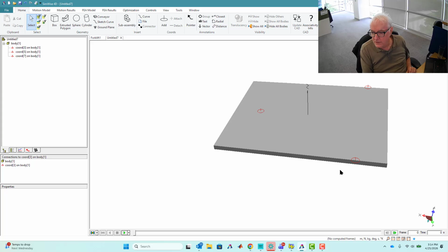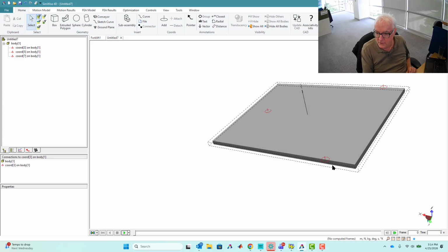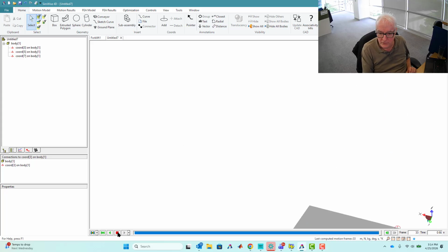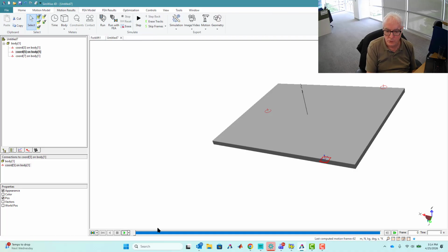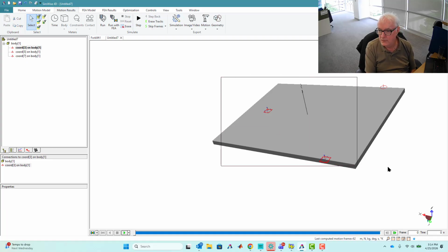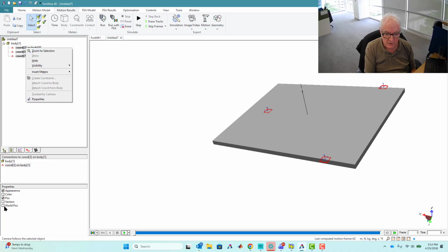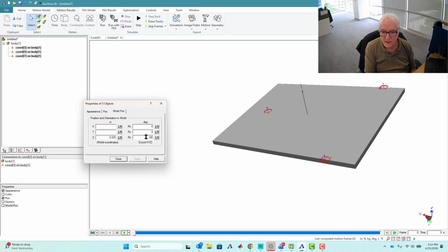All right, so these are just coordinate frames. They're just markers, attachments. It still falls with gravity. The basic idea, though, and I'm going to do this to the ground right now, is that we're going to attach to the vehicle through these three coordinate systems. If this one's a spherical joint, oops, I've got one more thing to do. I'm going to get all three of those frames again. I want to get the world position, and I want to match the orientation.